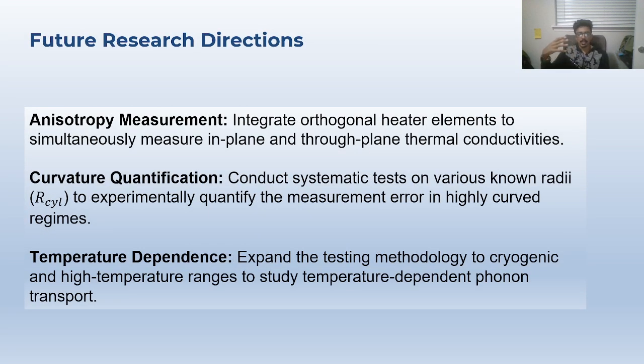So the future aspects for this research are these 3 points. We can do anisotropy measurement, wherein we can integrate orthogonal heater elements to simultaneously measure in-plane and through-plane thermal conductivities.